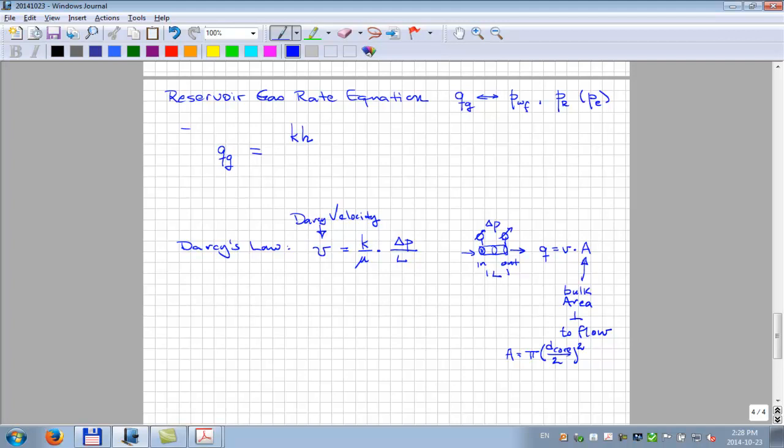But the flow is going through a 10 micron diameter tube, just one of it. That's a porous media. The whole thing is a porous media because you've got the one pore. So in that case, the porosity is, well, it's not very big. If this is 10 centimeters and the diameter is 10 micrometers, well, it's 10 to the minus fourth or fifth, whatever. It's a very small porosity.